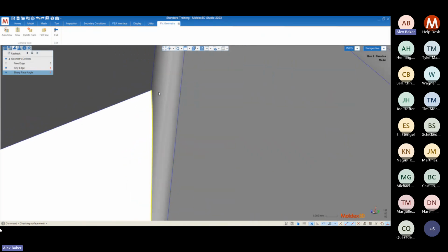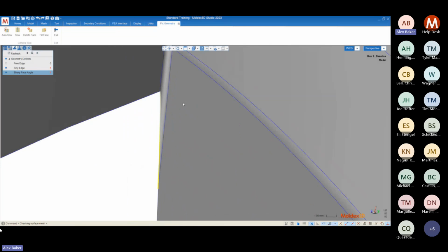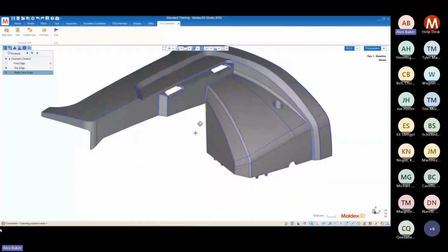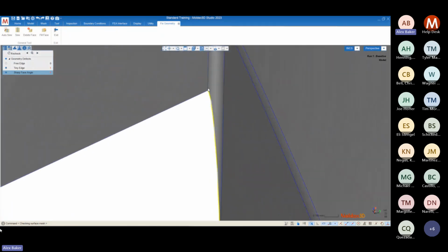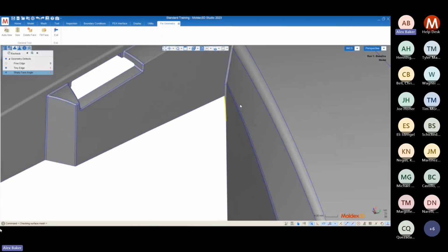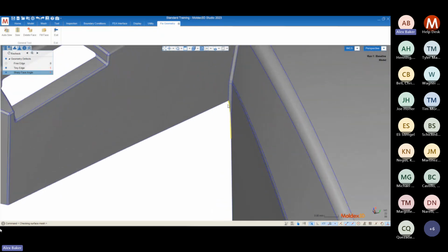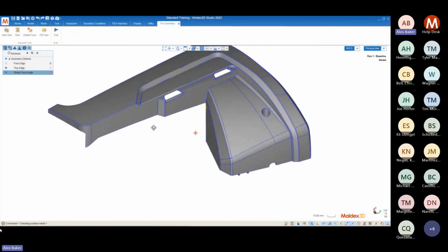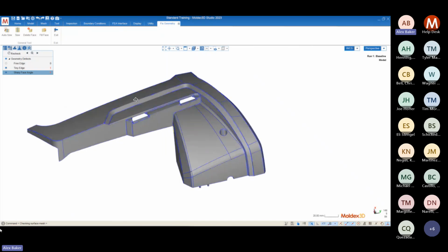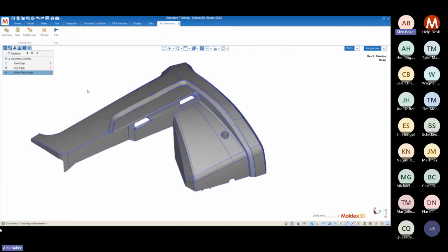And in some cases, you'll get a bad orthogonality error or any sort of other solid meshing error where we cannot fill in solid mesh in that small volume. In those cases, we might recommend to either remove the feature or try to open up that angle as much as possible once you get to the surface mesh. Again, these aren't make or break problems because they're not guaranteed to cause any sort of problem in the meshing, but we do recommend you to at least be aware of their presence.